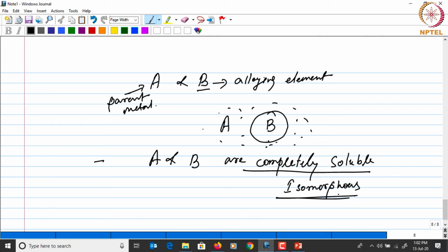Okay, so as you heat this mixture of powders A and B, the B will start dissolving in A, right? And the homogenization process, the distribution of B into A uniformly, will start to happen as the compact is being heated.